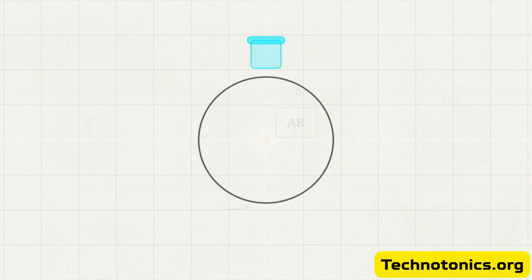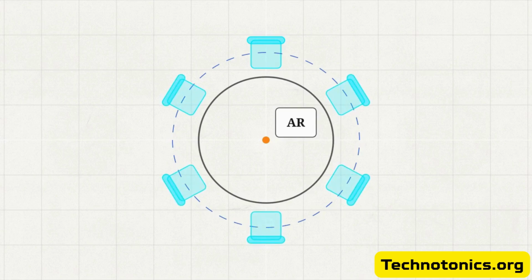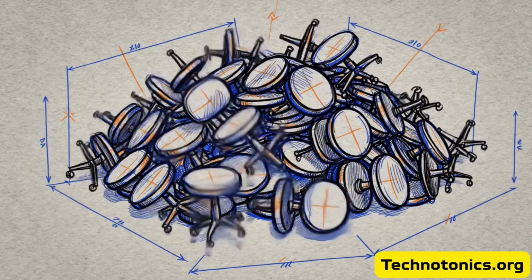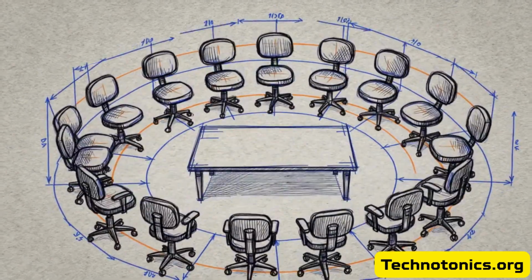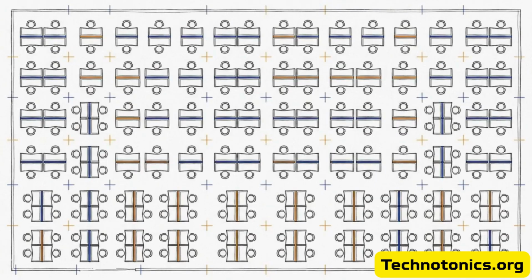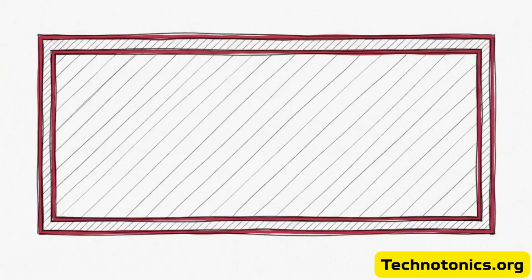If you're working with a round table, type AR for the array command. Choose a polar array, select the center of the table, and the software uses polar distribution math to multiply the chair around the entire circumference. Undo and redo function as safety nets, allowing you to quickly roll back a misaligned array or a misplaced copy without restarting the scene. Mastering duplication commands allows you to build out large-scale layouts by repeating simple elements instead of redrawing every chair manually. Review the completed layout.